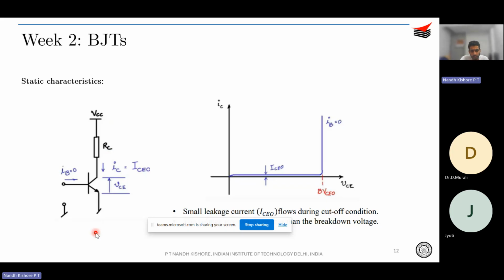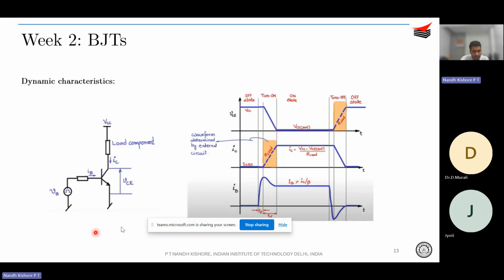Okay, so after you covered the static characteristics, you went through the dynamic characteristics. This is something we went through last week as well while studying drive circuits, right? That is, before yesterday. Here you understand that you start from over here, where IB was 0 previously. Then in order to turn on the device, you give a surge current of IB, which we called IB plus, while solving the problems. This should be about 2 times your normal IB on. Then you come to IB on, right? So if you give IB on, then what would happen?